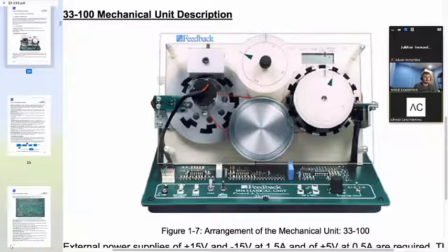No, but remember the whole idea. This voltage potentiometer will give you a voltage proportional to some physical characteristic. In this case, it will be position. So the voltage that comes in as the input will be a voltage, right? Depending on how much voltage this is, if it isn't zero, that means you don't want the position to be zero. You want it to be something else. So if the input isn't zero, you don't want the system to stay at zero. But if the input is at 0 volts, you want the position to stay at 0 degrees, or whatever units you have chosen.